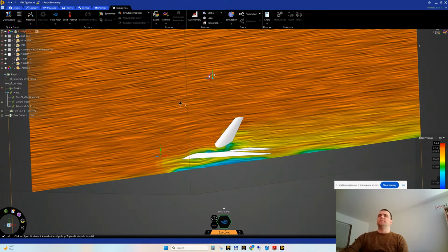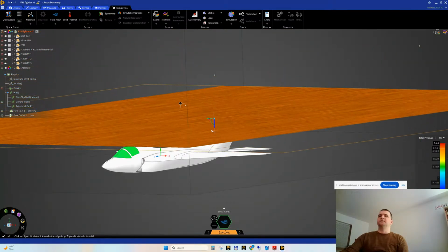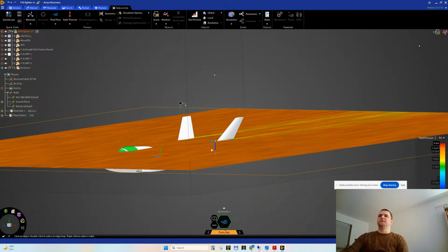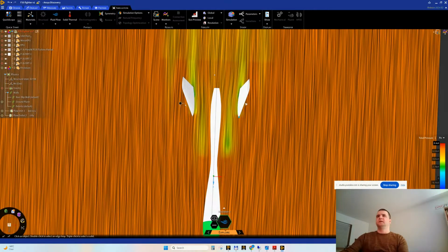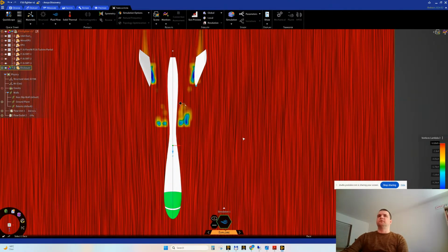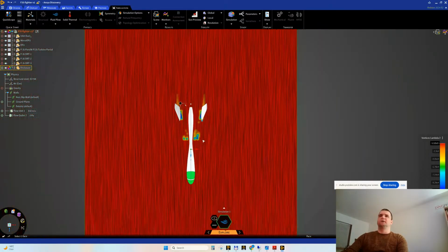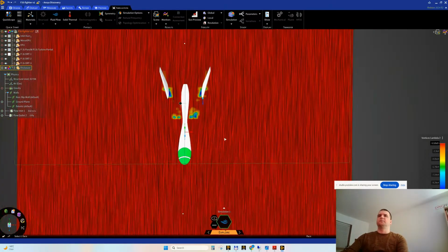Let's rotate the plane, something like this, and move it here to see the total pressure in this direction. Look here. You click these arrows or the small spheres from the global coordinate system, and you can see the total pressure, yes? Or even vortices lambda, yes? The place where the vortices will appear.